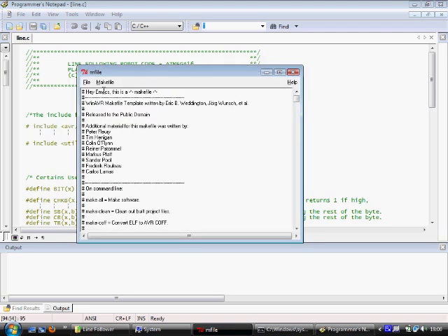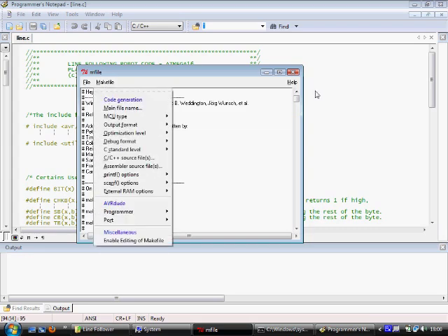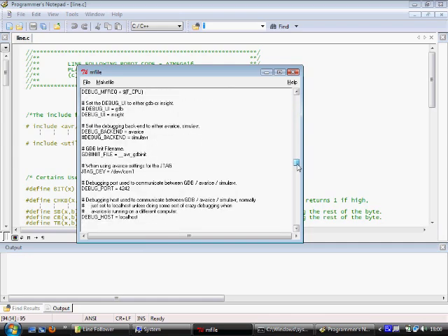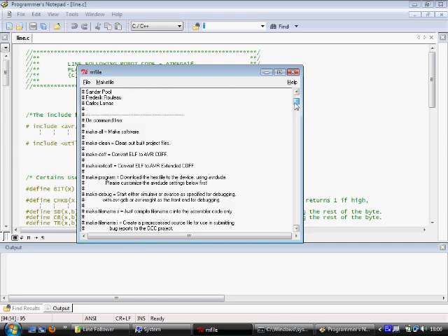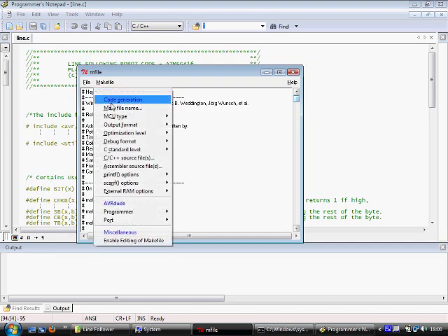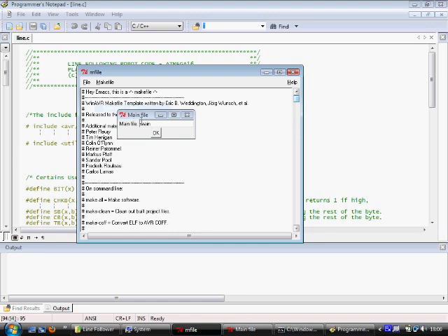Okay, so what you do with it is that you click on make file. See, the whole rule book is already made. It has all the sets of rules that WinAVR needs to compile this, but you need to make certain changes. Click on make file, then go here, click the main file name and change this name to line.